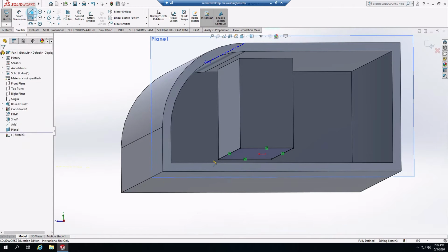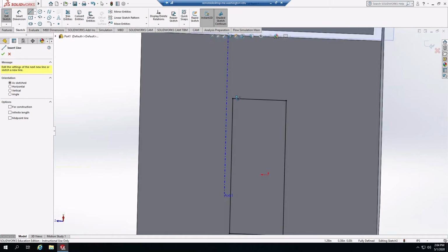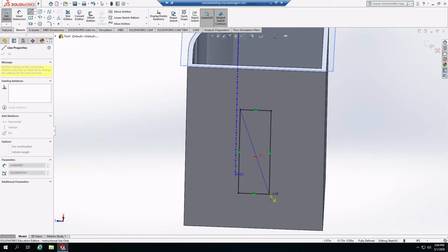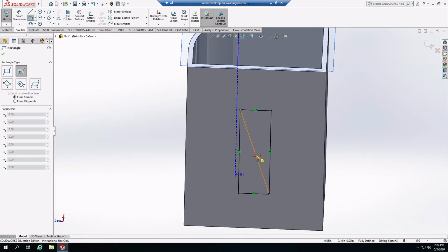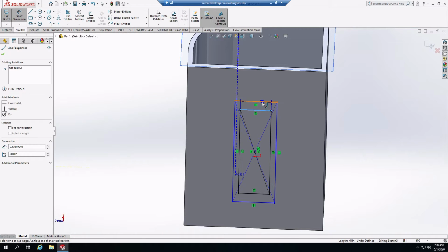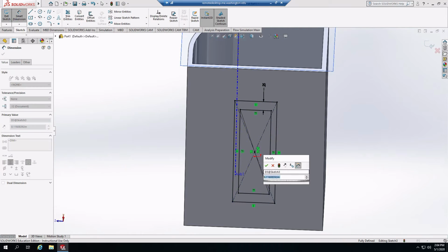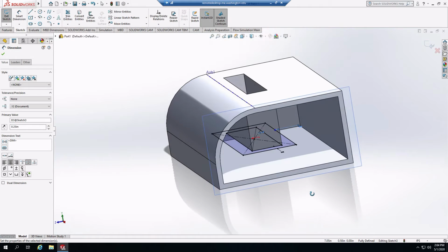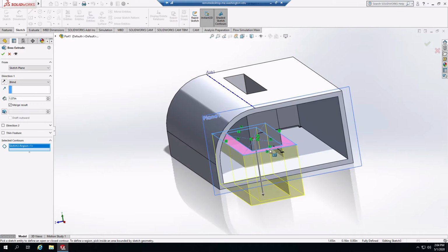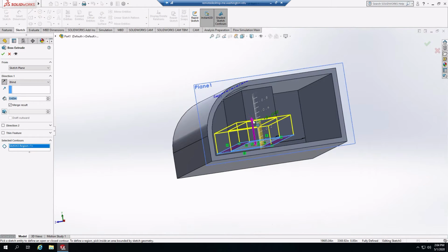Now for direct modeling, what we would do first off is create a sketch outline that we would then use to extrude up and thicken the walls. And so we can go ahead and do that. Do all the geometry and stuff, and then extrude that out into 3 dimensions and pull that up.